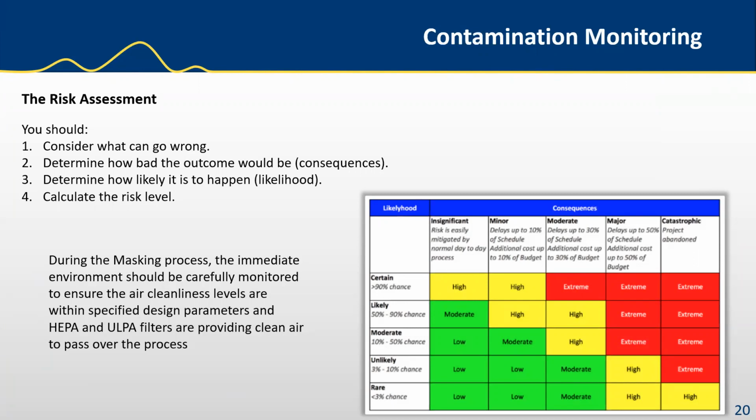For example, before the thermal oxidation or deposition process, chemicals are used in the pre-cleaning of the wafer. These chemicals would need to be routinely tested for particulate contamination. You do not want to introduce contamination into the process. So using liquid particle counters to monitor the cleaning chemicals really makes sense, especially the ultra clean water used for the cleaning processes.